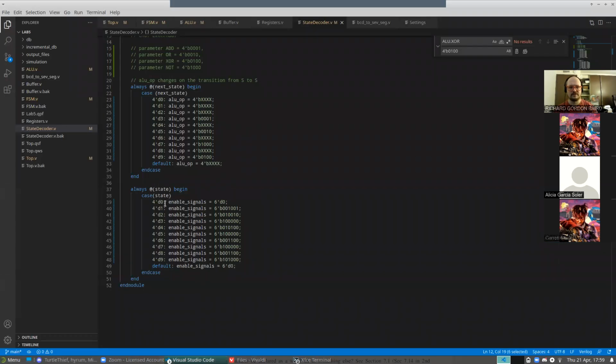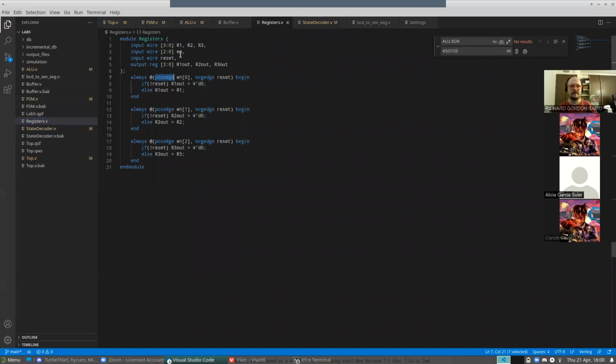Okay, so this is reset. I set all of my enable signals to 0. That's what it means to tri-state all of the buffs. And the reset of the registers is taken care of by its own reset signal that's also connected to the button on the board, where it will set all of the values to 0 for me.